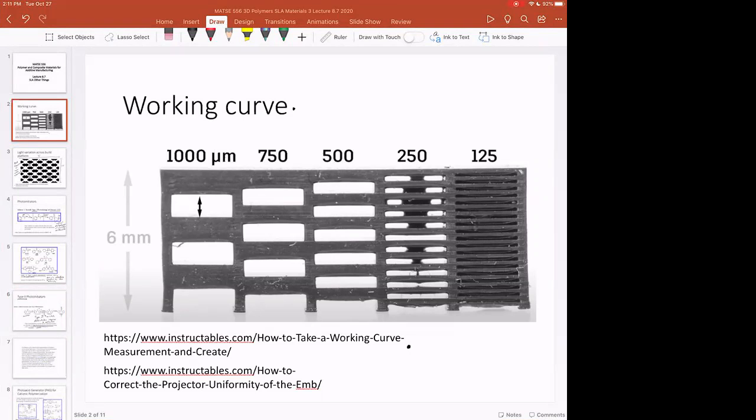Thank you. So I think for your project, or for people who are interested in nanofabrication, something like the Nanoscribe, I would encourage you to take a look at. The Nanoscribe is really interesting because it uses 2 photon resins, and we'll talk about those if we have time. They're just a little bit different type of resin than we're talking about here, but it's actually a very similar process to what we're talking about. However, it's on the micro scale, and it's done through a microscope objective versus the sort of regular size objects that we've discussed before.